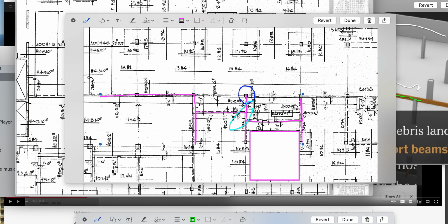So the vibration of this collapse was pretty much felt, I'm theorizing, only by people along this plane here. This is G. This was C row right here, and this would be G row. You call it lines if you like, I care less. All these are G's. Yes, one's turned different, and these are C's. But C here has a staggered deck. The load transfers out at this elevation. Remember, this is supposed to be 2'6". Now it's 1'6". That changes its ratio of strength across the face of it in the span.